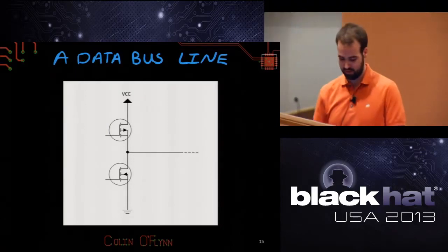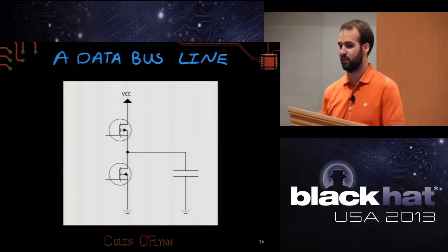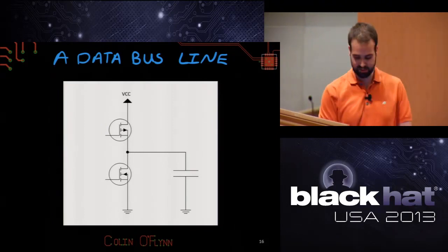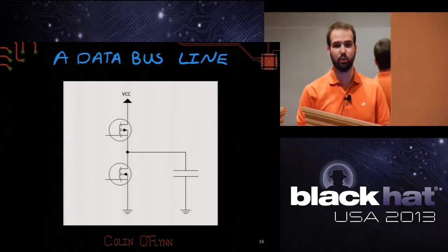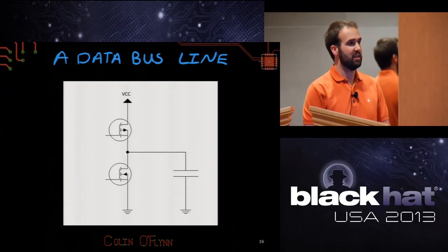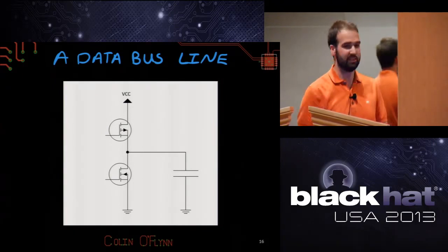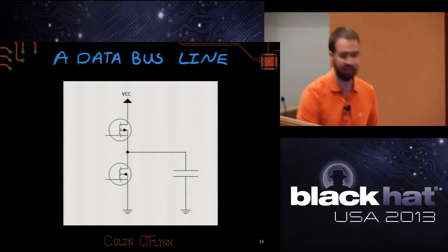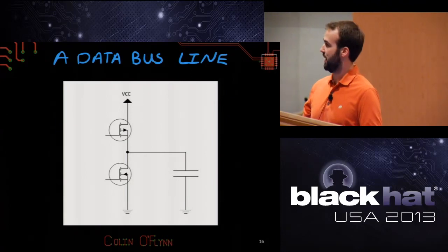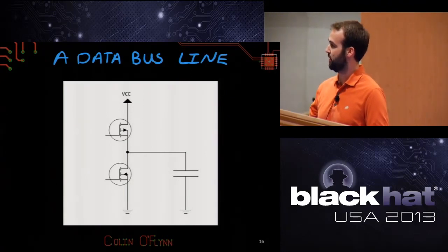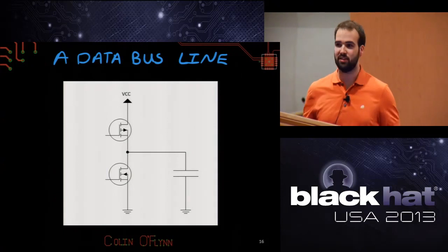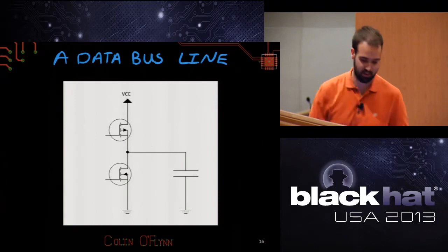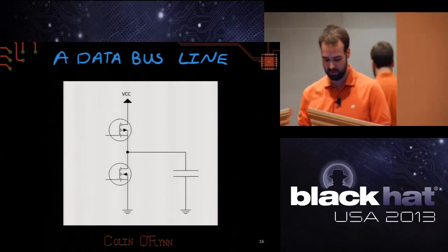This bus is effectively just a long wire, and it really looks something like a capacitor to the system. Now from high school physics, you might know that to change the voltage on a capacitor, to change the state, you're moving electrons. You're physically doing something. Physically doing something takes energy. So if you change it from a 0 to a 1, you're taking energy, power from this positive rail here, and it's going onto the capacitor. To change it from a 1 to a 0, you're taking energy from this negative rail to change the state of the capacitor. So it physically takes power to do that.